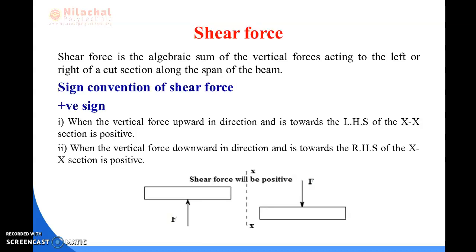First you have to know what you mean by shear force. Shear force is the algebraic sum of the vertical forces acting to the left or right of a cut section along the span of the beam.